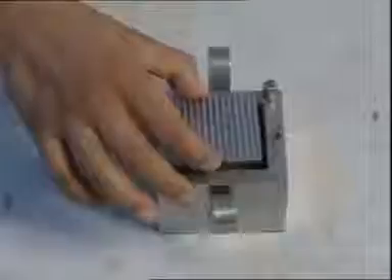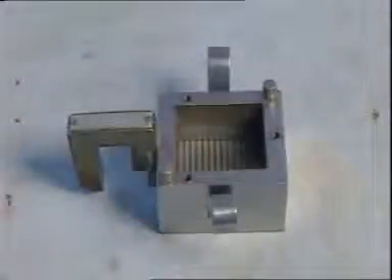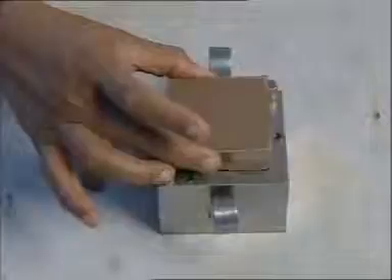Place one grid plate without perforations over the metal plate such that the grids are perpendicular to the direction of shear. Carefully place the soil specimen inside the box so that it rests on the grid plate.